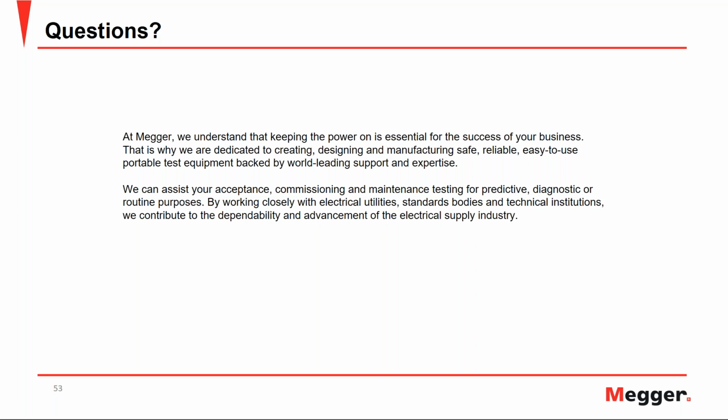The reason for testing at different frequencies is not that we are interested in finding the value at 25 Hertz or 70 Hertz or something like that. The idea is to see how the curve between power factor and frequency is behaving, and see the trend it is taking at the lower frequencies. And I really want to emphasize that the most critical frequencies that you need to look at are in the range from 1 to 20 hertz. That's where the curve really starts to take off on a problematic transformer.